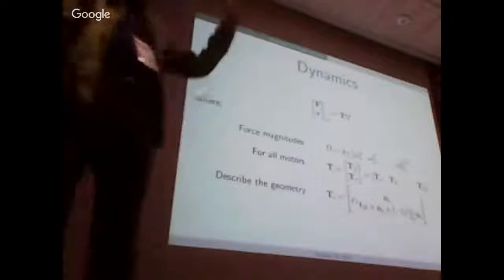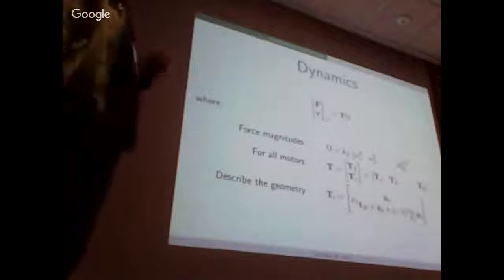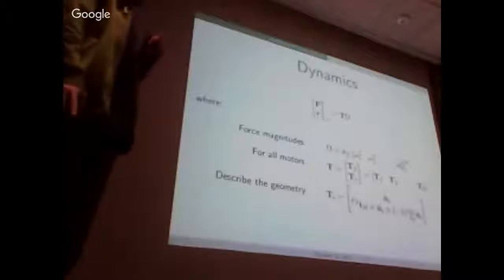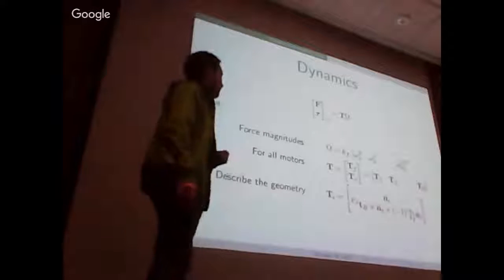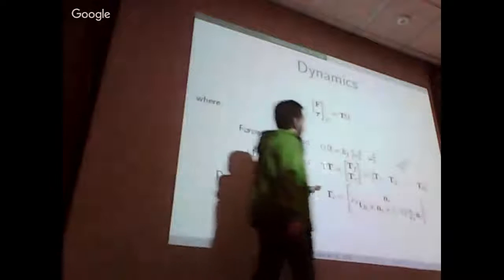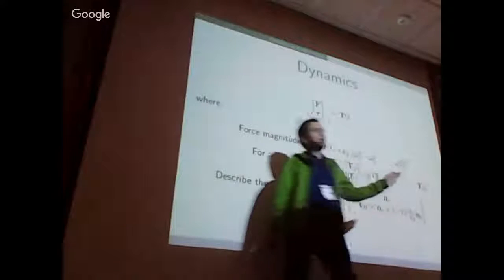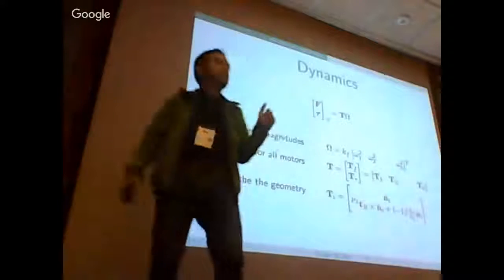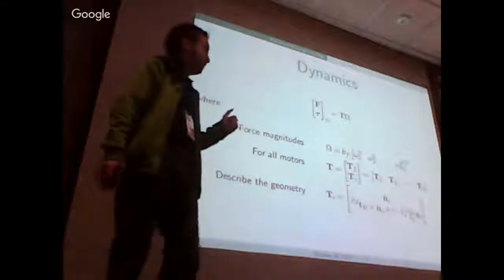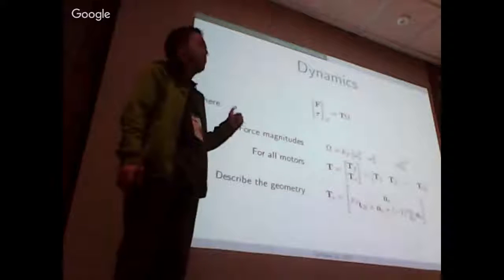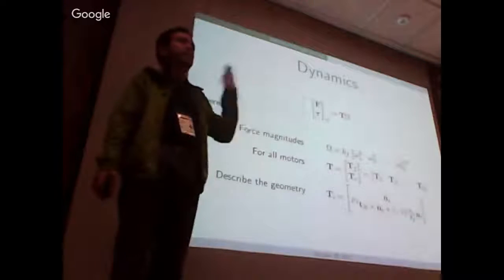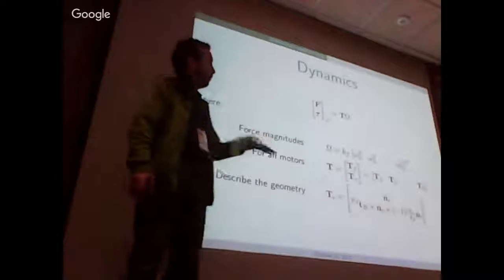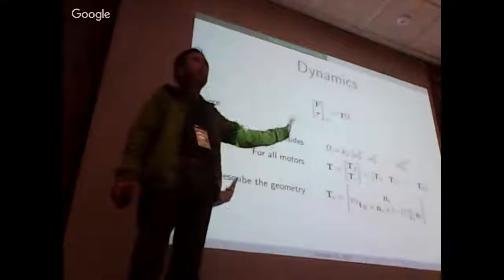Here I show you with the letter D the reference frame where the center of mass is located. And the transition matrix is given by 6 different vectors. Each vector is given by the configuration of each link. As I told you, each link can be reconfigured, and during flight, we can change the value for each of these.